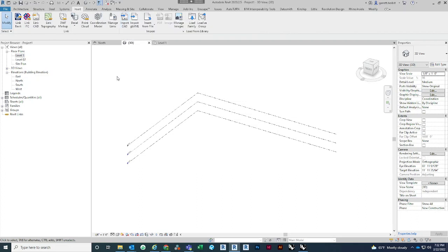Both are pretty much the same process. The major difference is that linking a CAD file means that you can import the geometry, place the geometry, and then if you go into your Rhino model and change anything, the geometry, the layers, whatever, and then you export it again and save over that file again, you can relink that CAD file and have it live update, and it will stay in the same exact position it was in, just update with the changes that you've made.